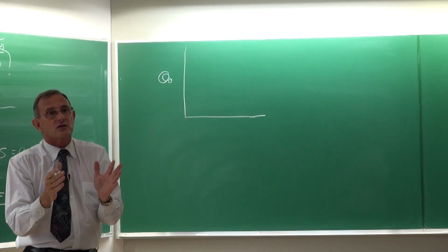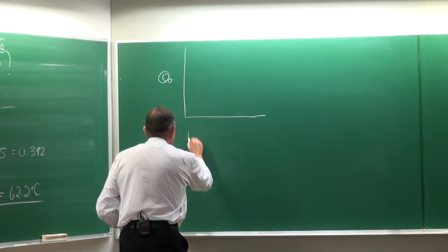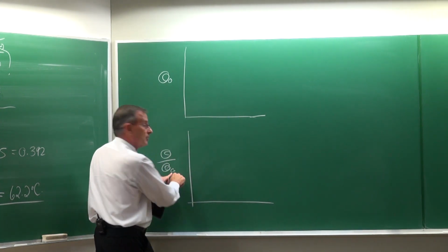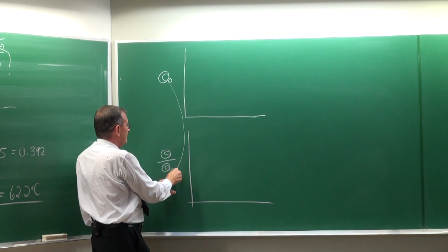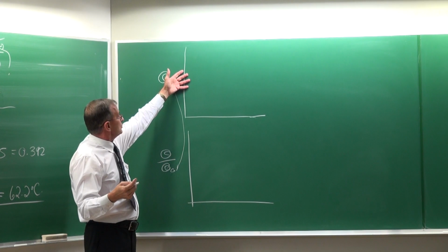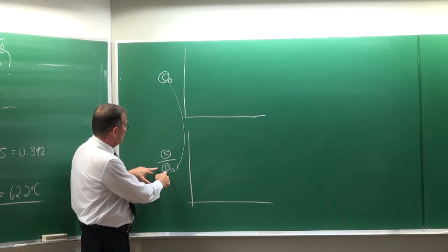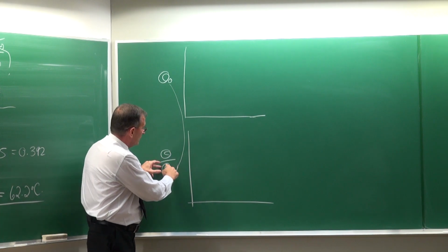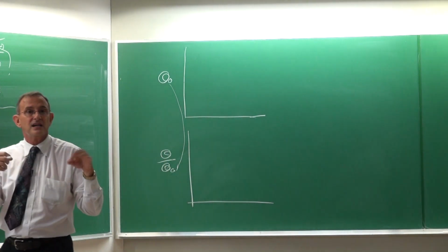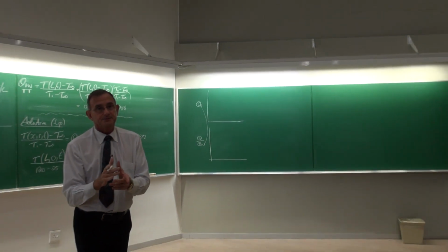And in most cases, we as engineers are interested in the temperature at the center. The second one will give you the temperature anywhere else, after you've normally calculated that value. So from the Heisler chart's point of view, it is always best to get it at the center first, but then you need to have it as a ratio. What you're now going to solve is the ratio of the temperature divided by theta 0. In the equations, it is not necessarily like that.